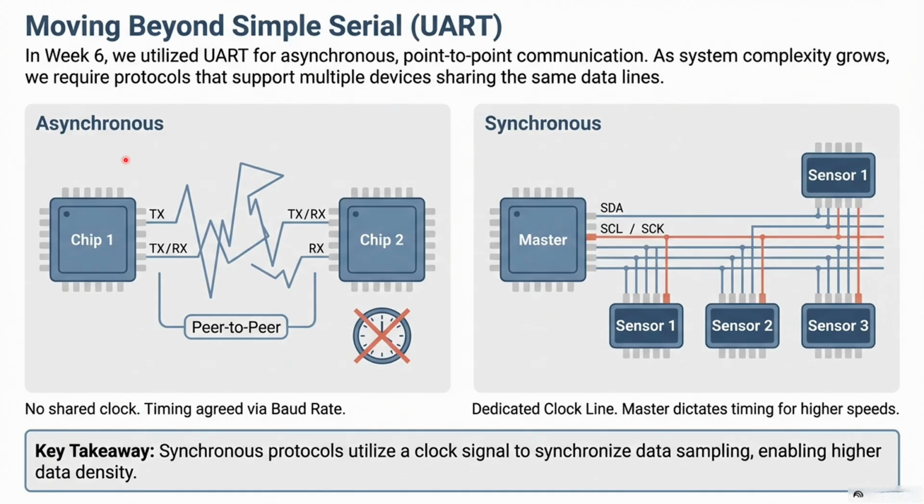Asynchronous, or UART, is the peer-to-peer relationship. There's no shared clock signal, so the devices must agree on that timing beforehand using a baud rate. Synchronous, as used in I2C and SPI, introduces a master, which is your microcontroller, that dictates the timing for everyone else.